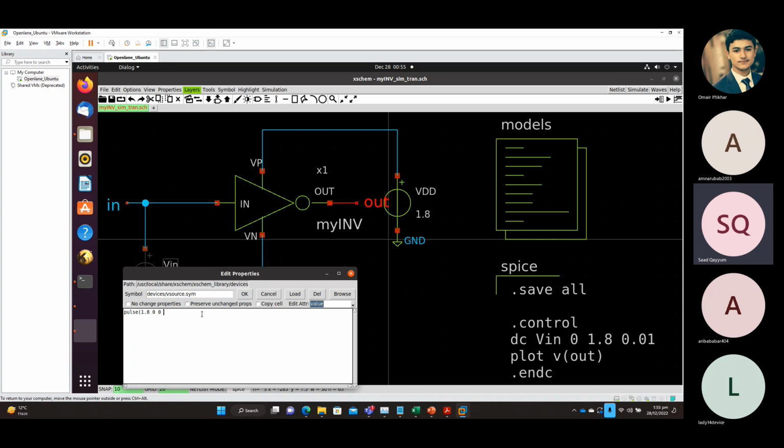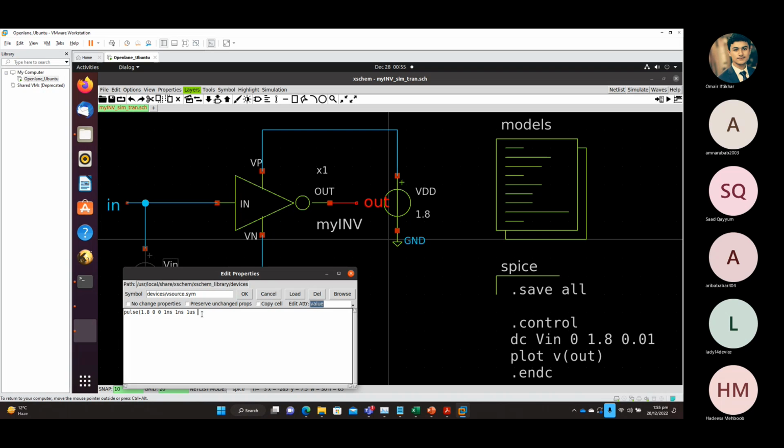Then the rise time of the pulse, so it would be, let's say, 1 nanosecond. Then the fall time of the pulse, which also should be 1 nanosecond. Then the time period of the pulse width should be, let's say, 1 microsecond, and the on time. I think T on. One of them is T on and the other one is the pulse width. Let's do it this way, 0.5 microsecond, and see.